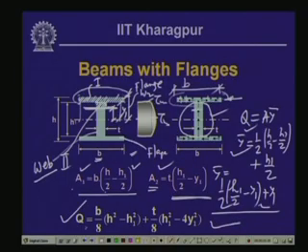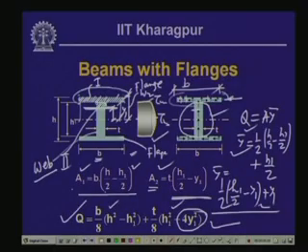Now, in this particular expression, if you note, except this particular y 1 square, everything else is constant. Hence, the shear stress varies again with respect to y 1 in a parabolic manner, in a quadratic form of y 1. So, if y 1 becomes 0, then we get the maximum value of the shearing stress, and when y 1 equals h 1 by 2, that gives us the minimum value of the shearing stress, and this is the distribution shown over here.